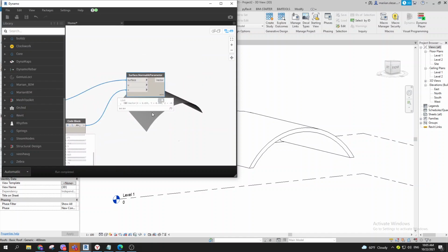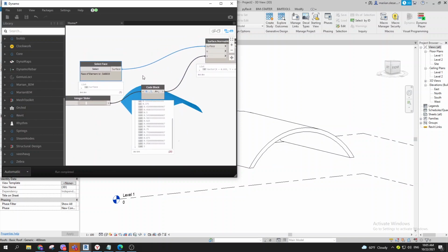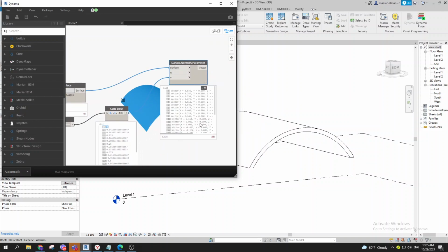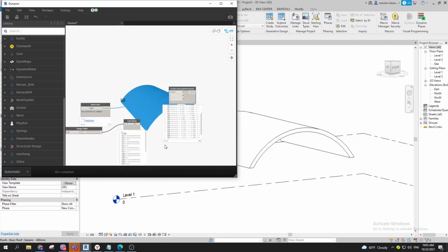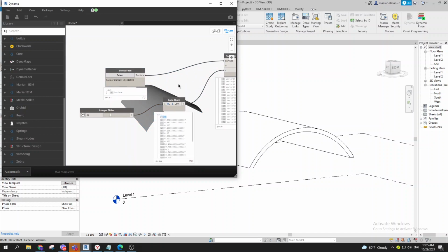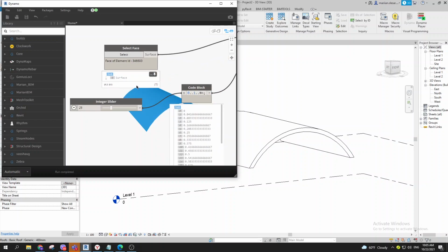So I'm going to get vectors. If you think about why it works that way, it takes one surface and it goes to one element. Even if I go to longest lacing, that will go through all of them. If you're not familiar with lacing, it takes one list and that list. As you can see, we have levels over here.